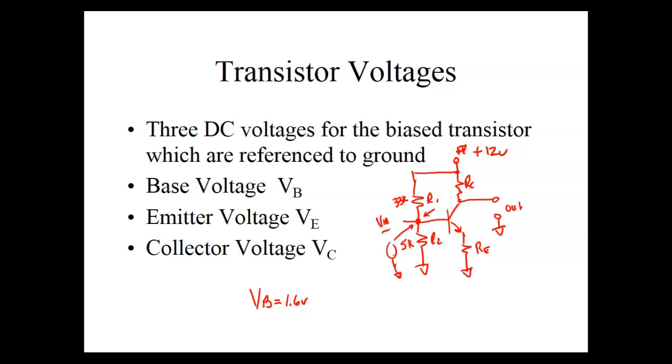All right. Now my emitter is pointing toward common. I have 1.6 volts there. How much is this guy going to drop? His forward bias, how much is it going to drop? It's going to drop about 0.7 volts. That means across this resistor right here, I should have around 900 millivolts. Is that right?